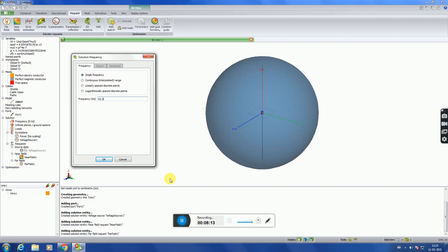How should I input megahertz here? Normally we write 93.5 megahertz as 93.5 into 10 power 6, right? So instead of 10 you need to put a small e, then 6. If you input like this, then the software will take this as 93.5 megahertz. So instead of 10 you need to put e here. In this way the software is built, so we need to follow the same thing. So now I have inputted the frequency as 93.5 megahertz.